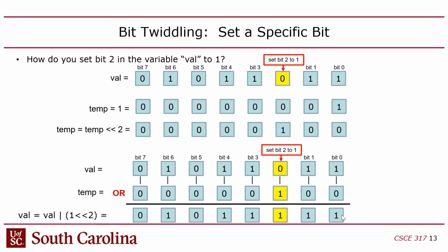because with hardware, you would read a control register out of the hardware, and then you may have to put some bits in a field, but if you screw up the other bits in that register, you can cause side effects. So a lot of times you just want to change individual bits or individual ranges of bits. So in this case, I want to set bit 2 to the value 1. I'm assuming that I've got val, I've already read it. It's in my register file, it's in my C variable.